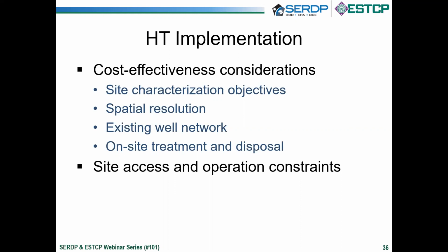The existing well will save you money. Instead of putting new wells to collect hydraulic information, you can rely on existing system to give you the hydraulic response and perform the pumping test. And also another consideration is the cost of treating the extracted water.